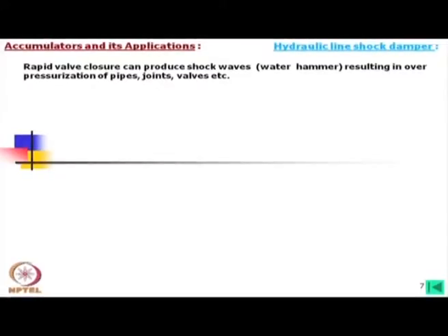And if we close the valve suddenly, what happens is the pressurized flow is blocked, and there will be a very sharp rise of pressure there.